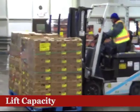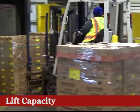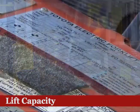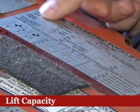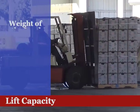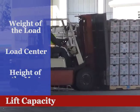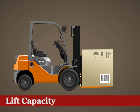Every operator must know the lift capacity of the forklift they are operating. This can be found on the data plate. It contains the manufacturer's recommendations for lift capacity. The lift capacity depends on 3 factors: the weight of the load, the load center, and the height of the mast. The weight of the load is just that. How heavy it is. Do not forget to include the weight of the pallets, or containers, when lifting.